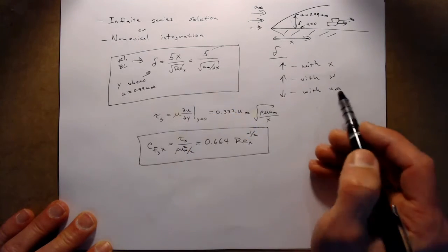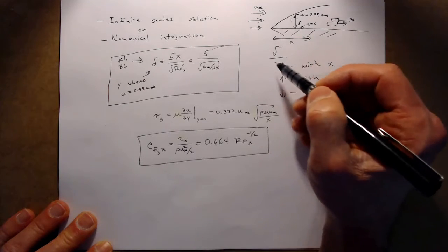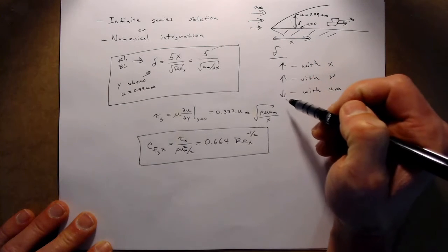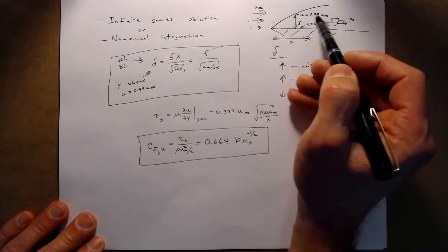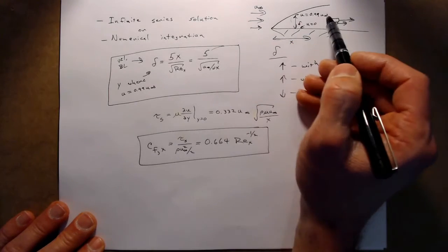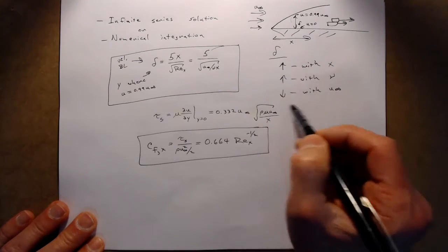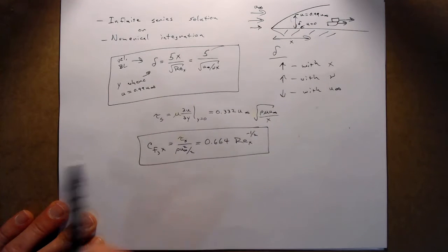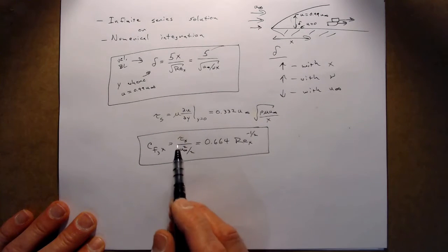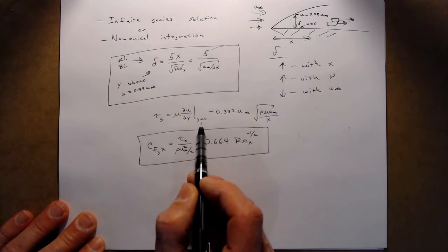And the other thing this tells us is that as the free stream velocity increases, the boundary layer thickness decreases. The free stream is able to bring more momentum in at a faster rate, and so that's going to decrease the boundary layer thickness. Now, once we have this solution, if we go back to our momentum equation, we can also solve for the shear stress at the surface.